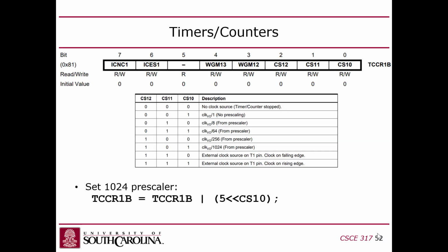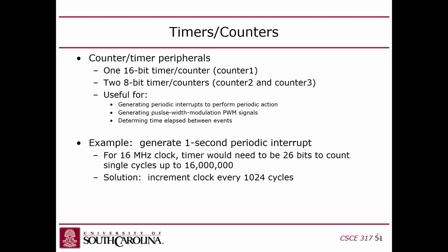Okay, and then there are also timers on this thing, which are really versatile because you can use timers for time division multiplexing the processor, but you can also use them for performance counting, like a cycle counter, if you want to check how many cycles it takes to run a section of code. They're also used for the pulse width modulation circuit.